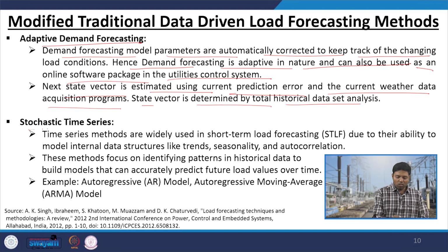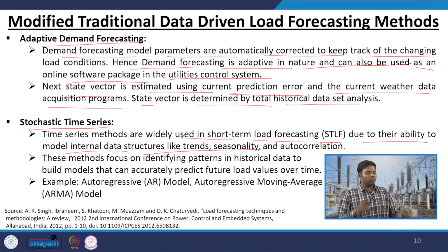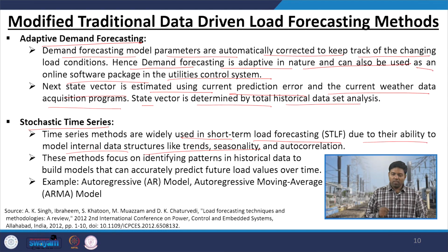Okay? Then you have the stochastic time series model. Time series methods are widely used in the short term load forecasting process, because this is mostly a time series prediction. At 12 o'clock this is the load, at 12:05 this is the load, at 12:10 this is the load. So, every time we normally do load prediction as a time series prediction, due to its ability to model internal data structure like trends, seasonality and autocorrelation. So, we will see how the seasonal variation or the trends in the load pattern are related with each other, and that correlation is validated.